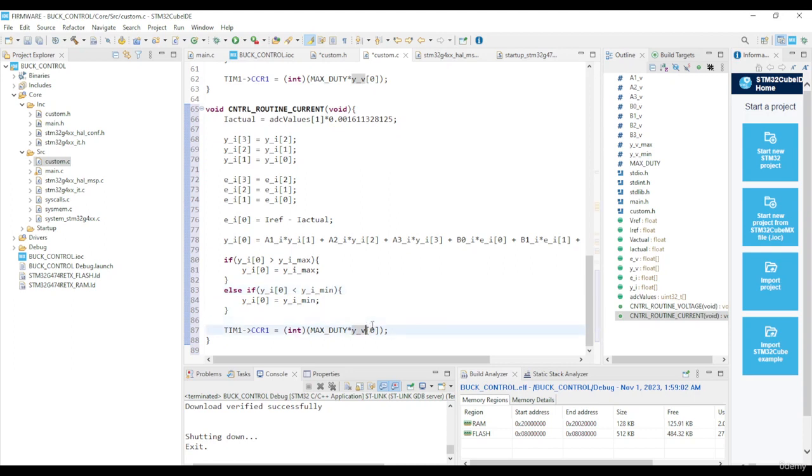And what you want in the end, you want to change that to I. All right. And also, because we're checking the I actual, there isn't a presence of a current sensor here, so it will still be the voltage that will be measured across the output resistor, but the resistor value is 7.5. And if I calculate 7.5 times 2.133, that's about 16. So we should see an output of about 16 point something on the output. So yeah, that's what we should get.